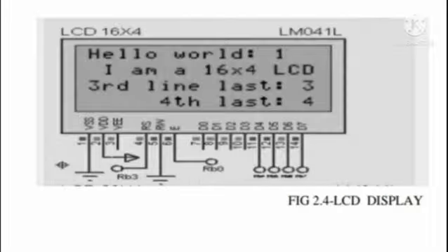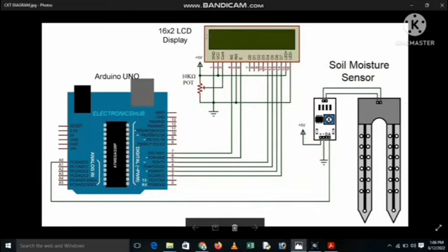As compared to the hardware, where there is a probe used to determine the soil moisture content, here, instead of the probe, we use the test pin, which determines the resistivity value. From that, we could determine the soil moisture content and the state of the soil also. In the moisture sensor module, the test pins, VCC and ground are located.